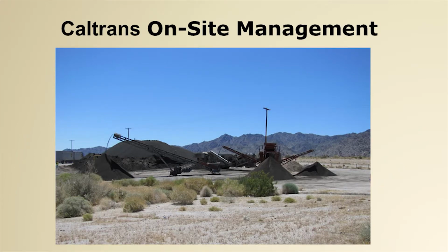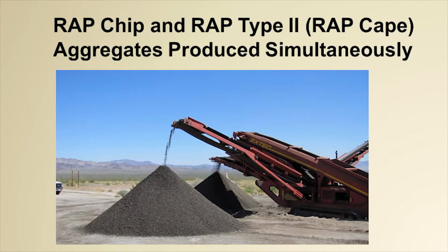It was a maintenance project, actually I-10, 60,000 plus vehicles a day, Interstate 10. We stripped off the AC in one location. They did a rehab or a milling on that, and then the maintenance wanted to put in a Cape Seal. So we came in and we manufactured both the chip and slurry simultaneously, set up the plant a special way, and then the maintenance crew actually applied the chip and slurry as a Cape Seal on Interstate 10.